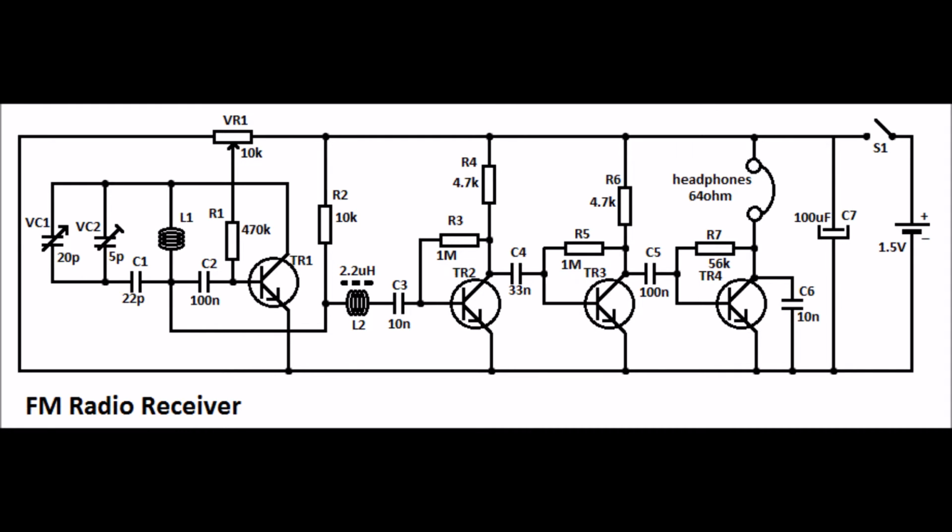Now we are going to tune the receiver to the required frequency. To operate the radio receiver, potentiometer VR1 must first be advanced slowly towards the end of the track connected to the battery positive until, at about the halfway point, a sudden slight increase in background noise will be heard, indicating the onset of oscillation. It should then be backed off very slowly until oscillation just stops. It then should be possible to tune in some stations.